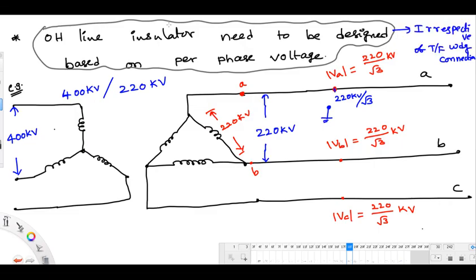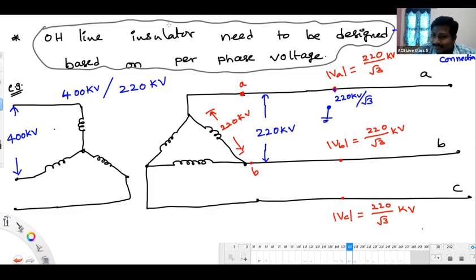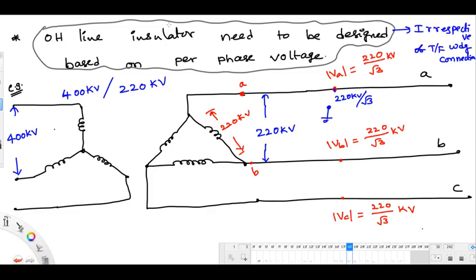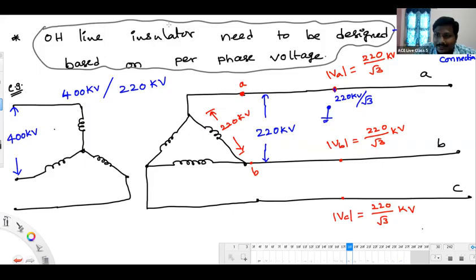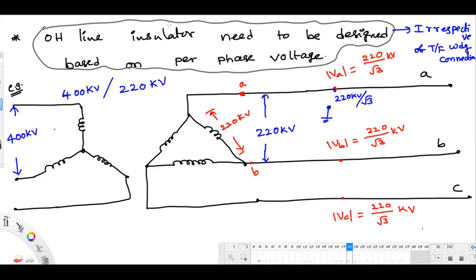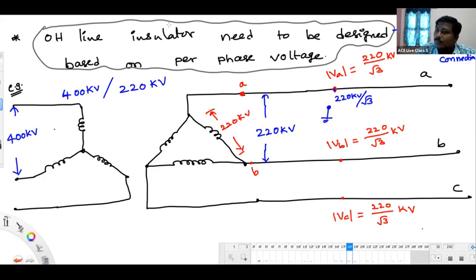You may be under the impression that if you disconnect the load, current flow is less, voltage is high, because drop is less. That's a steady state concept, right? But in the transient period, whenever we are disconnecting or connecting the circuit, there is a change in the current flow as well as the voltage across these natural elements, inductors and capacitors. Because of that, a definite transient is going to be created.